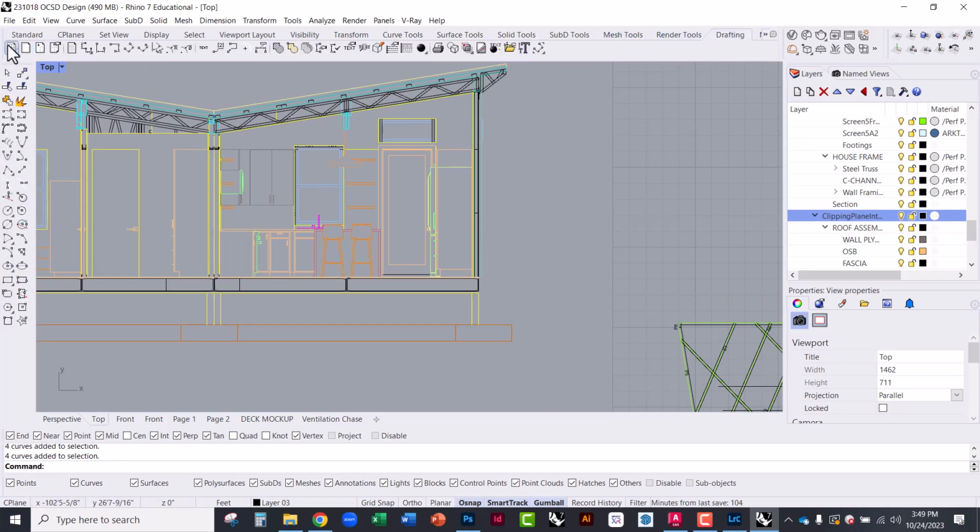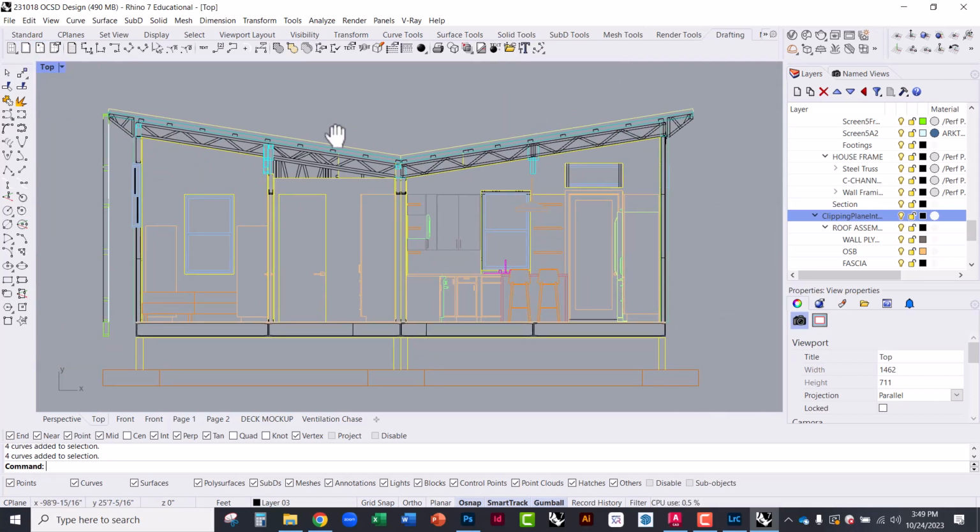So in Rhino, you have the ability to create layouts and sheets. What a layout is, is basically a 2-dimensional drawing that you can place viewports on. So if I want to have 5 different views on the same layout, I can do that. I can have a floor plan, a detail drawing, a 3D view, all on the same layout. If you go up here to layout and left mouse click, it'll give you a layout with 4 details. So I can click on that.